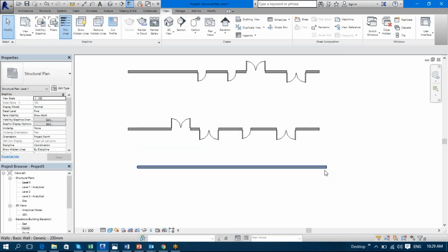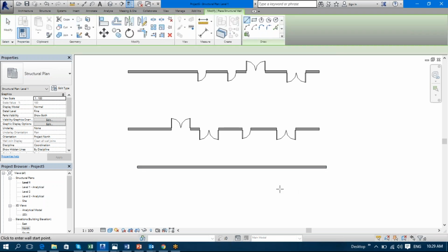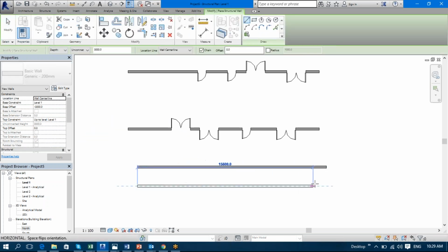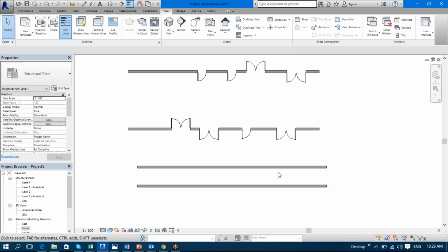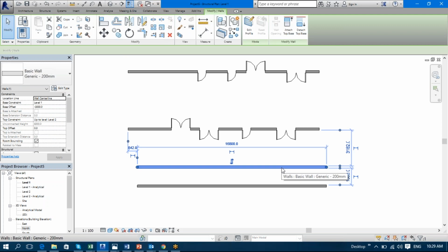Okay, so if we go here, now we have created a wall architectural, right? Now I'll create a wall structural. If I select this wall structure from here to here, now what will happen? If above I have told you about the 5 principles, now please observe these 5 principles. The moment I select this, there is a contextual tab which is showing I can change and modify the profile of this wall, or I can modify this wall in this way.